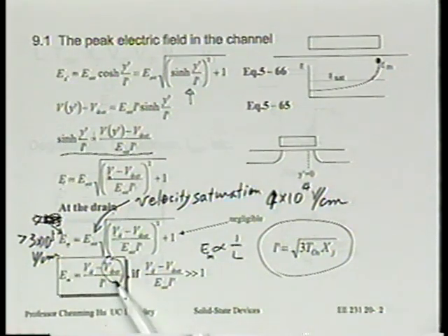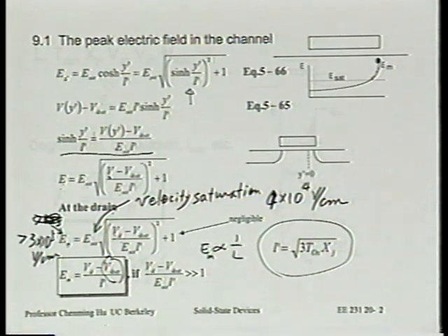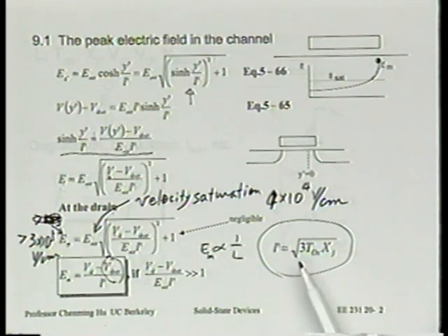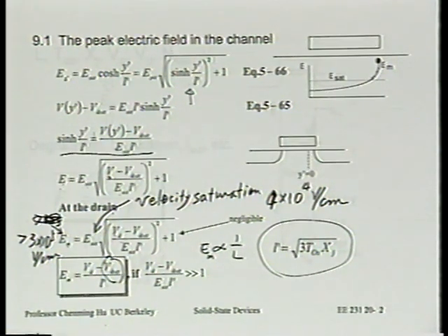So the L dependence comes through this VD sat term. And certainly it's a function of VD. That's why we always have some maximum power supply voltage a transistor can be operated at. And what else does it depend on? It depends on oxide thickness, and on the junction depths. You may ask, well, does it depend on the doping concentration? Now, according to this particular model, to first order the substrate doping concentration is not as strong a factor as these highlighted factors.